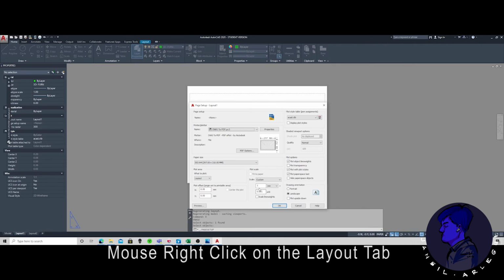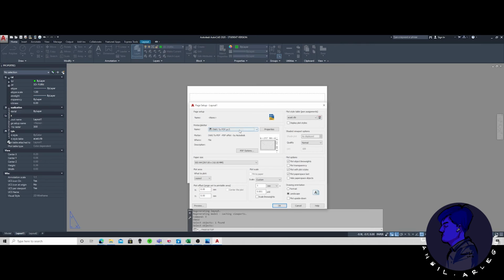Okay, so pretty much this is the setup, since I'm running in meters. So 4 things that you need to touch for this are the plotter and the scale. So 1 is to 0.001 because we're dealing with the scale of millimeters to meters.